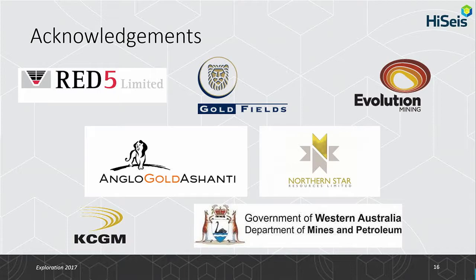Just wanted to ask you on your acquisition, are you using a single source or are you using multiple sources per shot? We have used both, but typically we use a single source, whether it be vibrator or explosives or weight drop. Given the steep dips and the need for high resolution, we believe that that's a better approach, and that fold is a better way to build up our signal to noise.